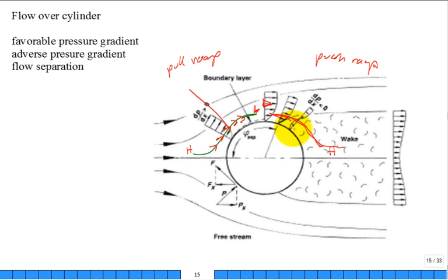But it's hard to do, especially when the flow is close to the cylinder, meaning it's slower, it has lower kinetic energy, and yet it's going into a region of higher pressure. It's slowing down, but it was already slow to begin with, and so then it'll get where they're showing you this velocity profile kicks back. See that? They're showing you this velocity profile where it kicks back close to the surface. That's where you get the point of separation.